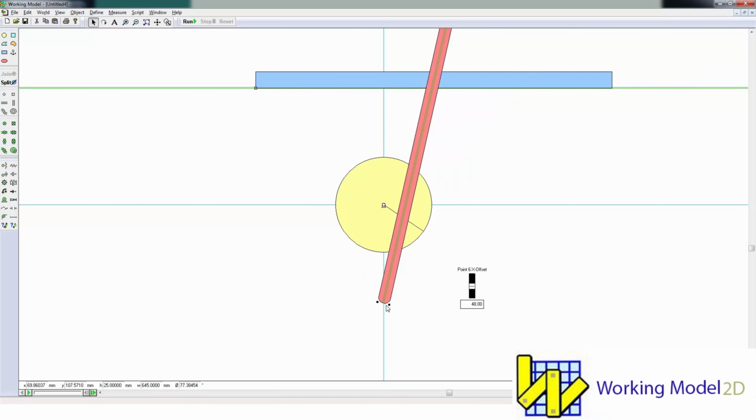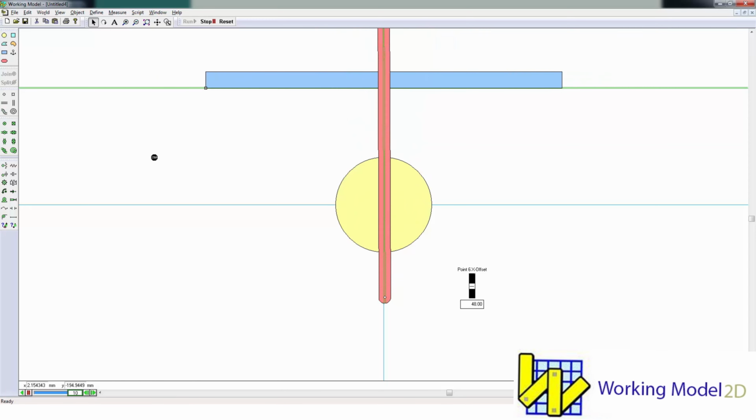Okay. All right, and then let's maybe drag this down to some position at the 6 o'clock position down here, and we'll just create a pin joint. I'll click on the constraint, hover over the edge of that, and it wakes up. So I've just created a pin. And for the position here, I could also do something like create slider controls that vary the position. So it would allow me to investigate many different scenarios.